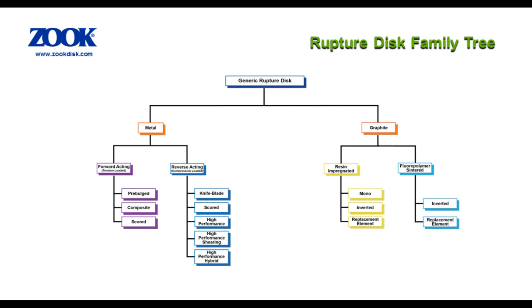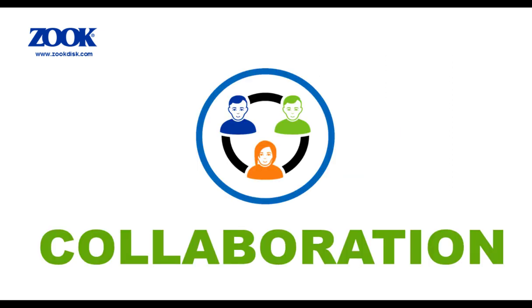A patented fluoropolymer sintered process involves preparing the graphite substrate to accept the fluoropolymer in the form of both liquid and powder. The coated graphite is then sintered at high temperatures that produce a highly bonded coating to the raw graphite, resulting in an impervious material. In addition to all the resin-impregnated graphite features, the fluoropolymer sintered process has greater corrosion resistance, higher operational temperatures, FDA approval, and a non-stick finish amongst its benefits.